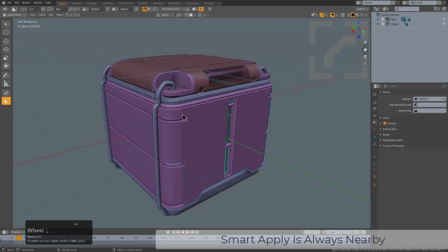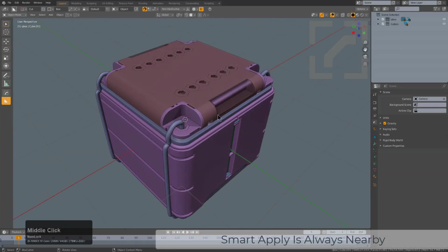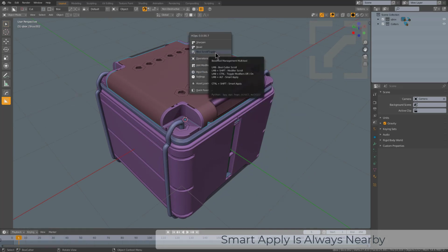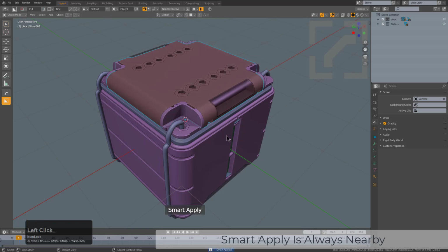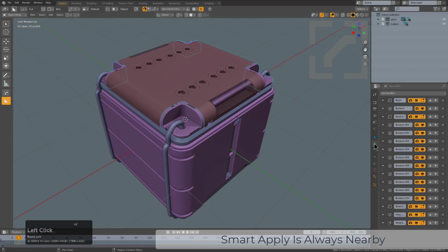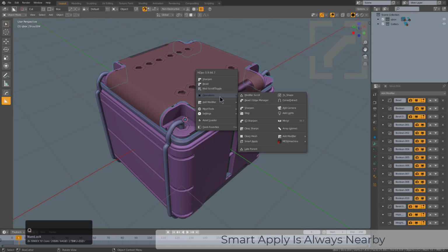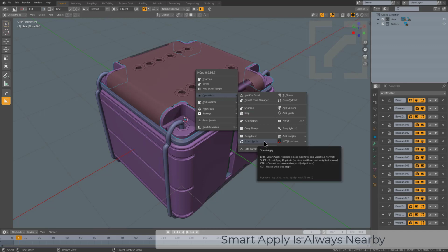Due to the importance of Smart Apply, there's actually too many ways to locate it. So if we select an object, we can press Q, and if we look under Mod Scroll Toggle, you can see that either Alt-clicking this or Control-Shift-clicking this will run Smart Apply. So I'll use Control-Shift-click just in case I was using Emulate Numpad, and we see that we're able to Smart Apply, except this one is kind of a quick Smart Apply, running the utility version, so it doesn't actually display all the information. So we'll select another object, and for this one, we'll locate the Smart Apply located under Operations.